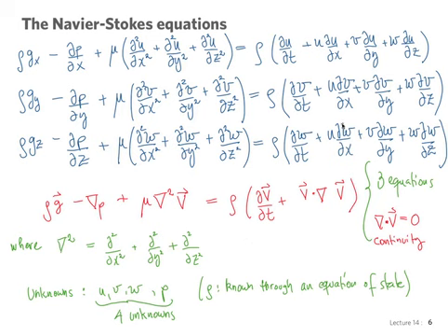Remember we called these nonlinear terms here. You can see clearly here that these are nonlinear, right? u du/dx. All of these terms are the nonlinear terms. These are what makes the equation very difficult. The convective acceleration. They appear also in the Euler equation. So the Euler equation is basically just as difficult as Navier-Stokes because we've got the nonlinearity. That introduces a lot of fun things.